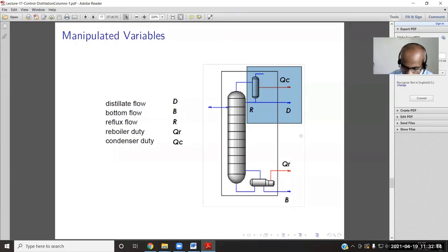Thermodynamics la you studied last semester. So from the TXY diagram you can always, what is meant by a TXY diagram? This T and distillate, no? Distillate is a liquid and the corresponding temperature is known. So temperature and composition have a correlation. Okay, so simply measuring the temperature, we can take control action.